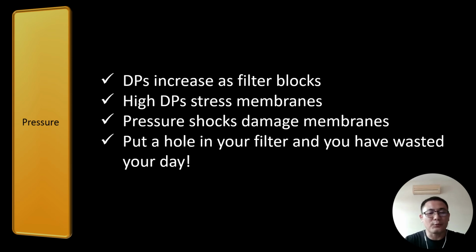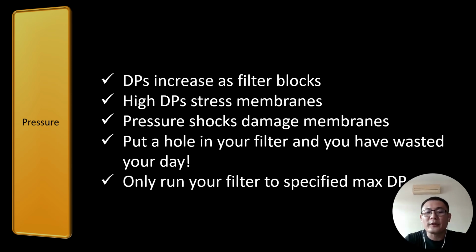If we try to push a big size of product through the pore by force, what happens to the pore? It will open up and become enlarged. Subsequently, it no longer retains the microbes effectively. If this happens, then your filtration job will be wasted. How do we check the pore size is adequate to retain the target particles? We can perform microbe analysis on the product to ensure the results are meeting the specification. Do remember to run the filter at the specified differential pressure.